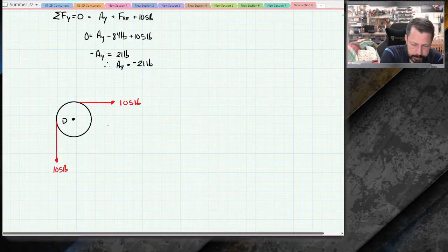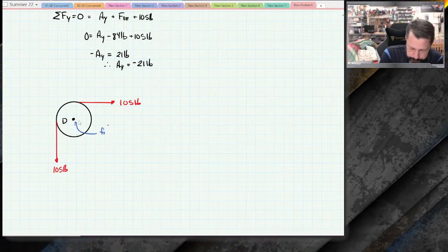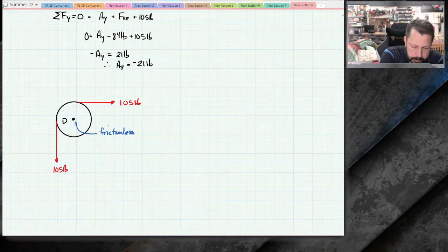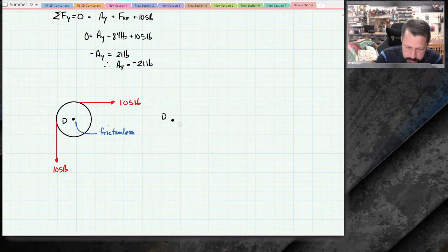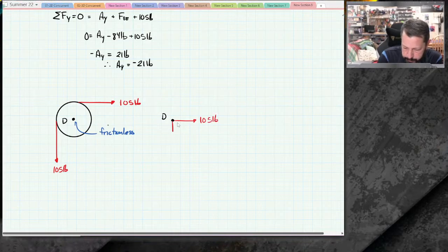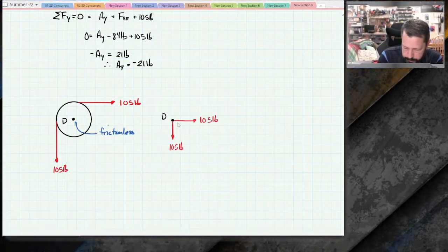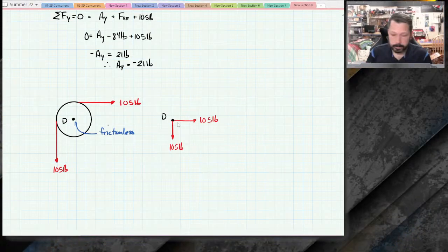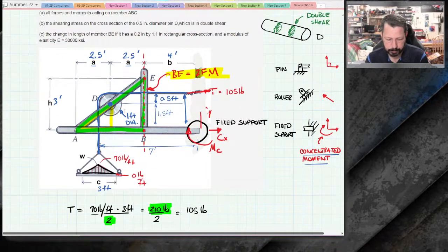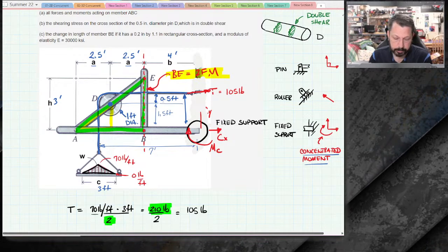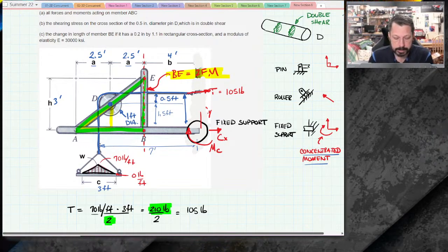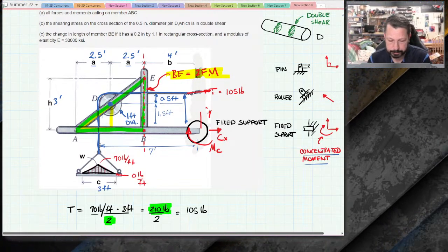As long as this pulley is frictionless, then if it's convenient to you, you can take point D and put those cable forces right at point D. So that could have actually been a little bit convenient for us earlier, right? When we were trying to figure out these moment arms, and we were having to add half the diameter of the pulley, these 1/2 feet here and there. Maybe that would have been useful to just put the tension right at point B, and it would have saved us a little bit of effort.